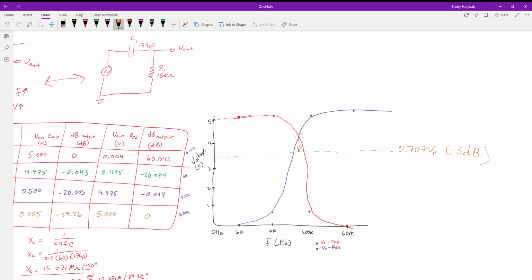It's just very, very roughened. But the idea here is, at this point where you see this negative 3 dB, this 0.707 of whatever our max voltage, anything that is above that line, we want to pass those frequencies through without changing at all. If it's below this line, we want to attenuate the signal so it gets down next to nothing.